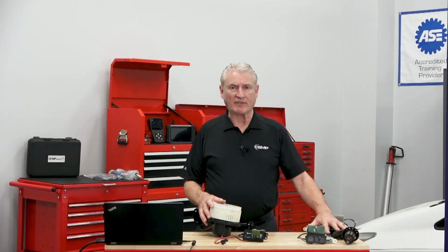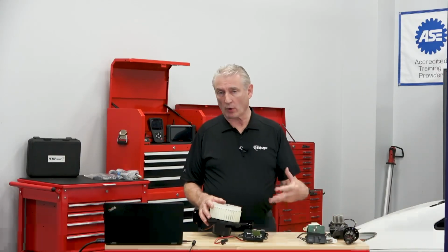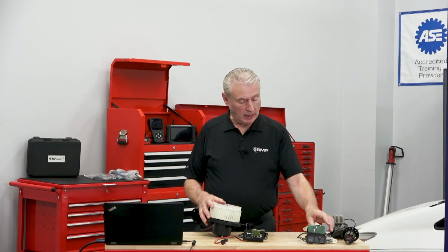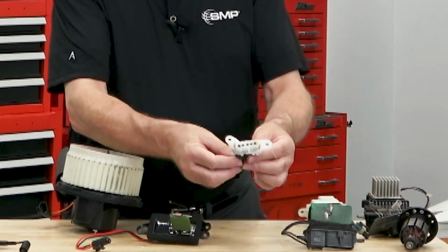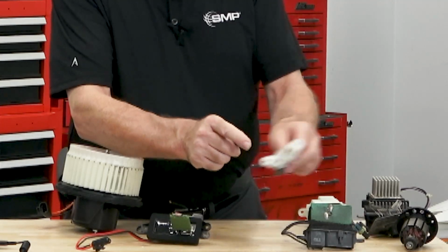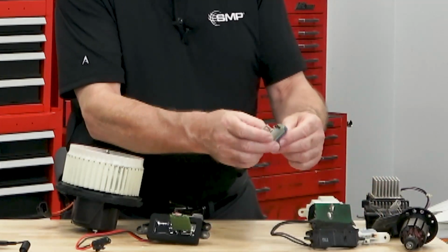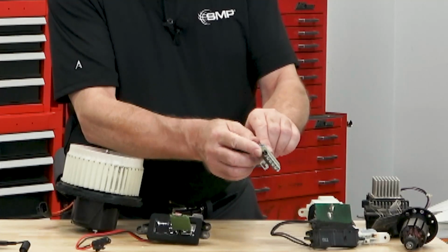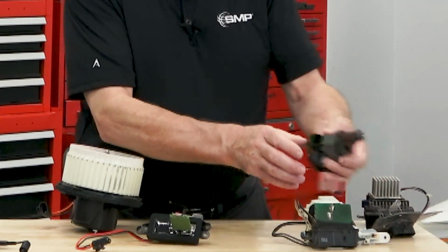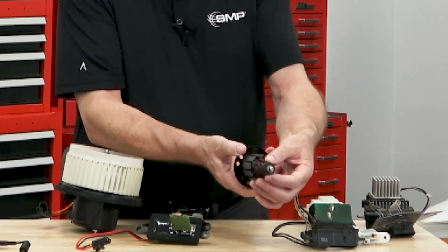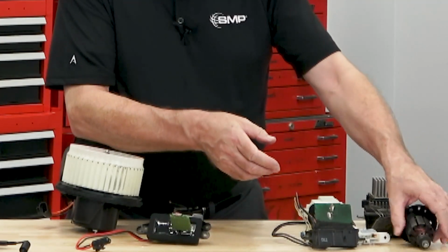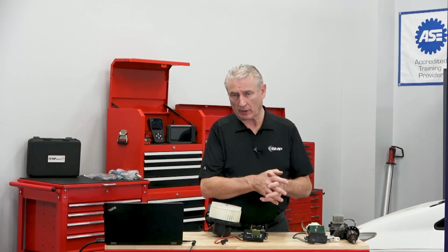So here on my left, I've got a series of failed blower motor resistor circuit components. You can see here I've got an actual blower motor resistor. It's got a burned terminal here. Here I've got a conventional resistor pigtail connector, and you can see it's got a terminal here. Here I've got a blower motor, and you can see that the segments are pretty badly worn and burned. A series of issues can sometimes lead to repeat blower motor resistor failure and poor blower motor performance, and oftentimes it can be difficult to figure out just exactly which of these components might be the issue.